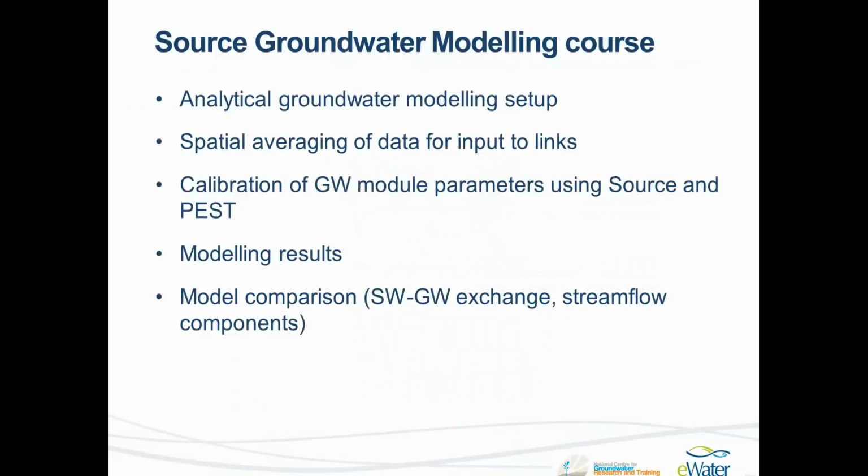And I'll go through how to calibrate the groundwater module parameters using Source and PEST. I'll also present some of the modelling results from this work, and I'll go through those comparison points and show the differences between the surface water groundwater exchange and the stream flow components, so the total stream flow and the base flow. So I hope that gives you a bit of a flavour for what I'll be talking about.